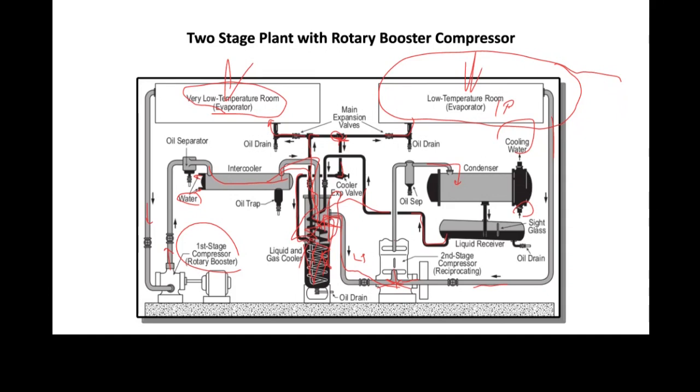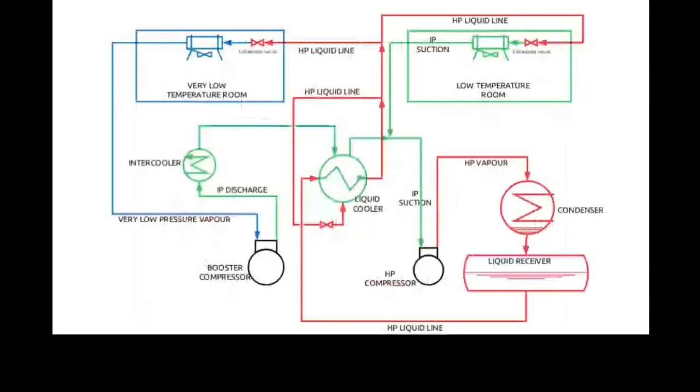Okay, so we are subcooling the liquid refrigerant using this cooler, which uses the combined effect of the cool gas leaving the intercooler, as well as it's fed with refrigerant directly. So in fact, it's kind of like an intercooler as well. Just a little bit more of a complex design. Now, if you have trouble following along with that, what I've done is I've taken it and drawn it out schematically. And again, there's a full description of that in your lecture notes.